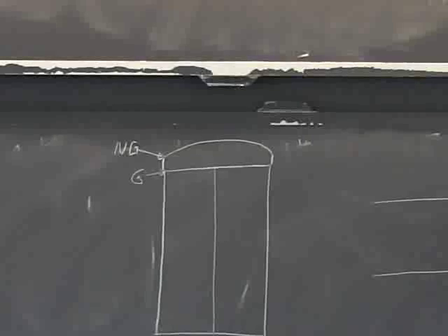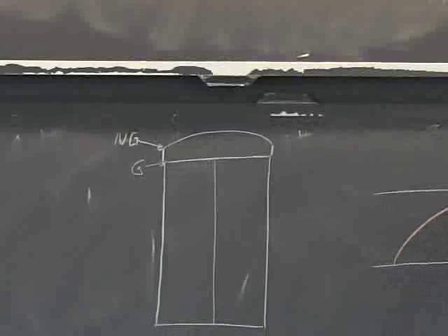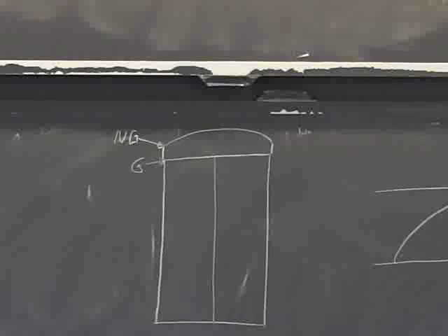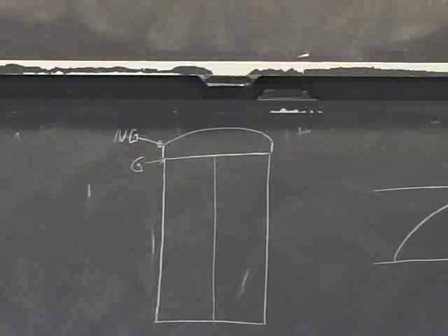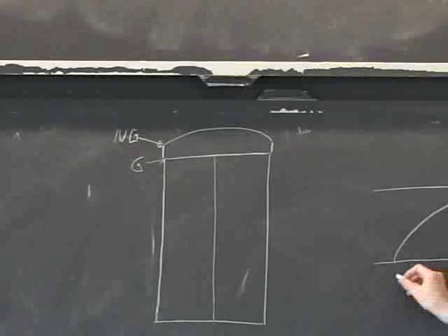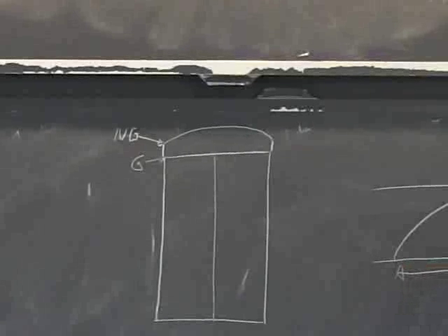Our objective is to grow a crack, say like this, so an aspect ratio of 2. From here, going towards the inside, so our A here is 1 inch. And if you're looking at the schematic for the semi-elliptical crack, we'll put this as 2 inches.